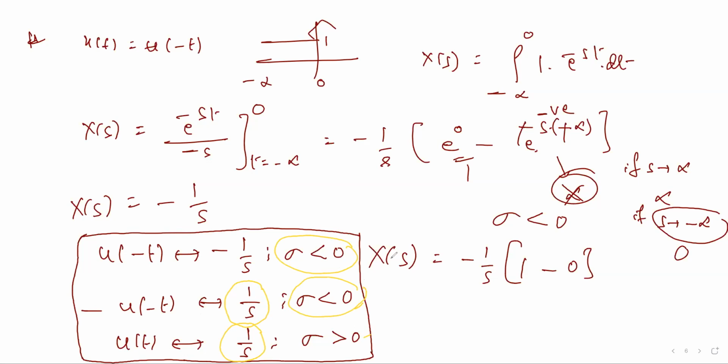So any two different signals cannot have both Laplace transform and ROC same simultaneously. Anyone should differ, otherwise inverse Laplace transform we cannot find. There should be some one-to-one relation to find inverse Laplace transform properly. Noted?